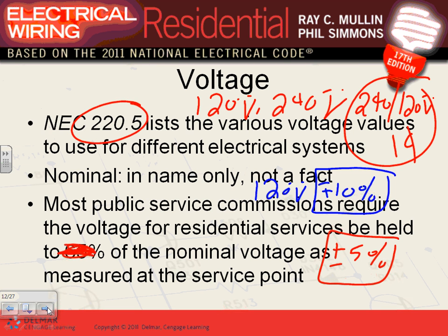Any questions, guys, about the voltages, nominal voltage versus actual operating voltage? How is the voltage controlled down the line to try to get that 5%? Oh boy, it's a whole lot of how the utilities control the voltage to stay within this. They have capacitors and reactors and transformers and taps. It's a topic. Let's open this topic when we go into the industrial. But believe me, they have a lot of stuff that they can control it. Caps is a big deal.